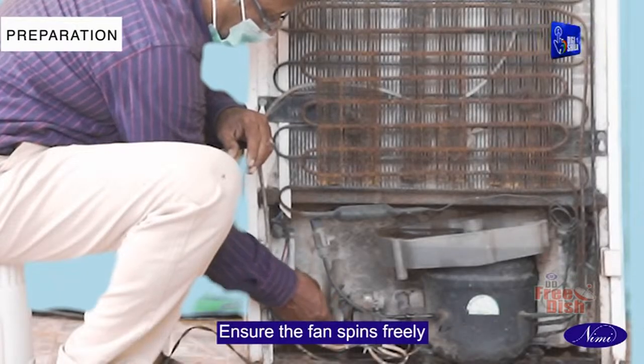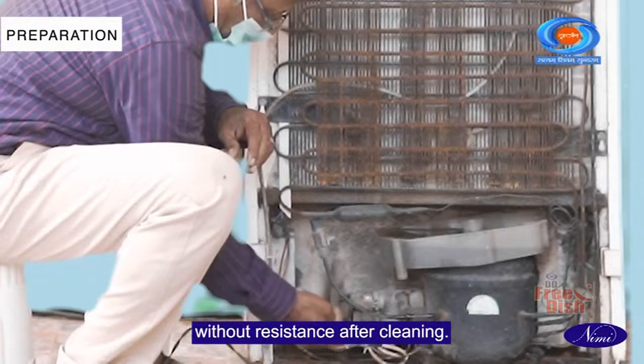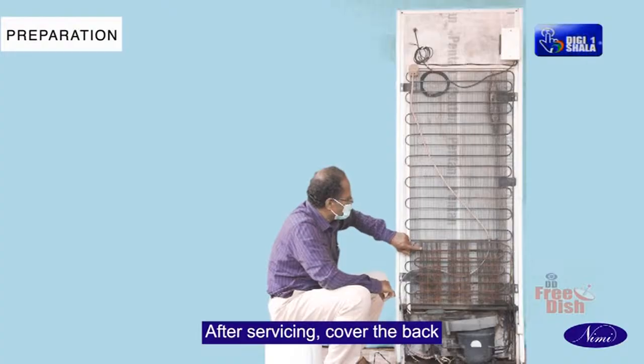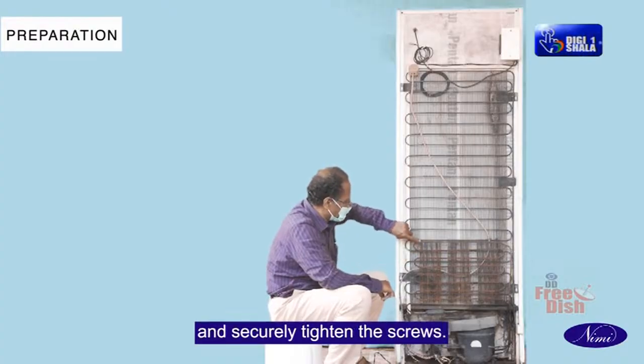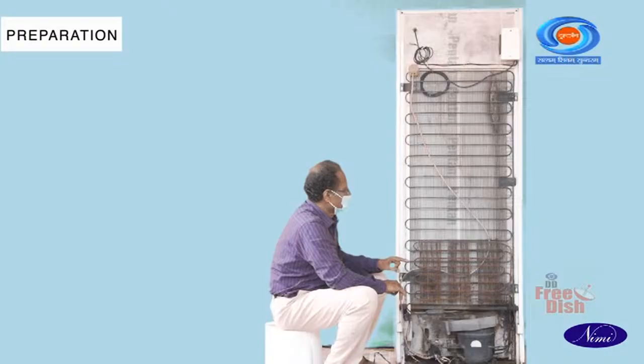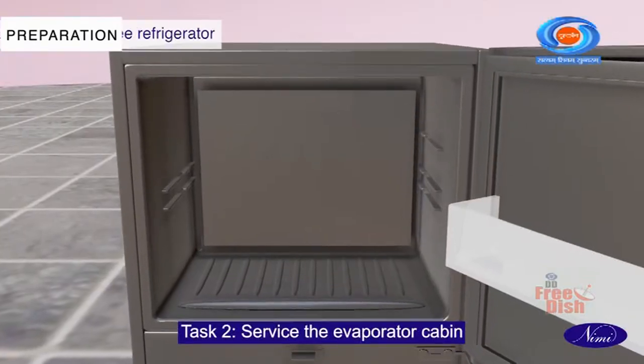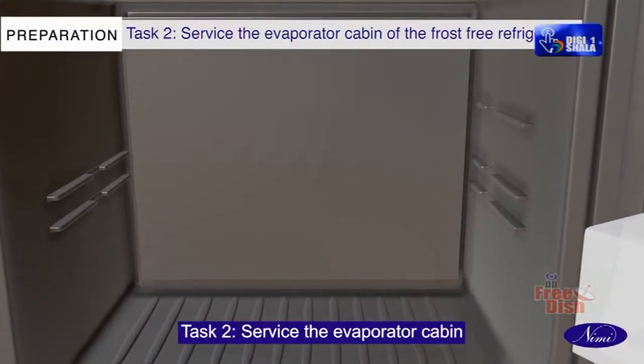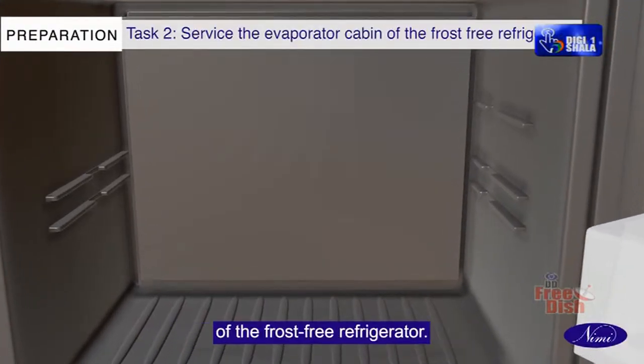Ensure the fan spins freely without resistance after cleaning. After servicing, cover the back and securely tighten the screws. Task 2. Service the evaporator cabin of the frost-free refrigerator.